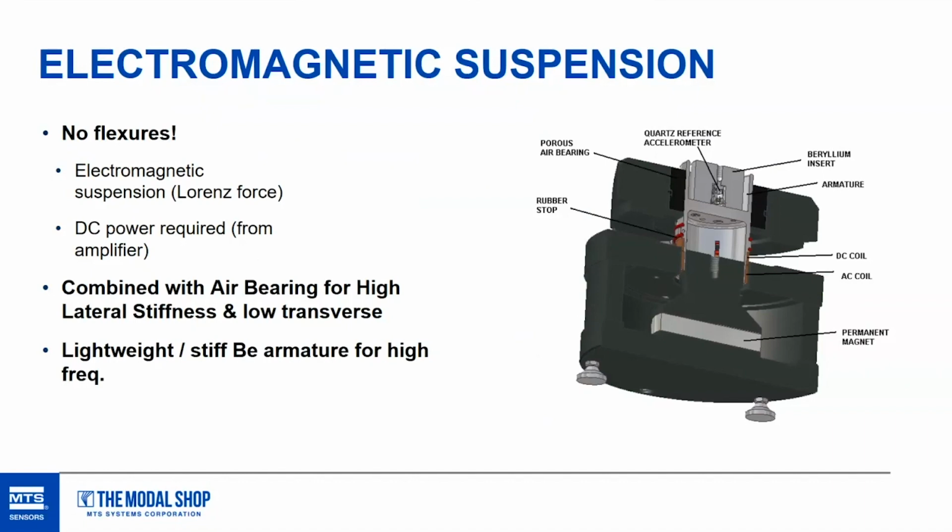The shaker is only going up and down and almost not having any type of jiggling or any transverse motion that can affect calibration. And that's a pretty common issue with flexure-based systems, flexure-based shakers, but with the air-bearing design, you pretty much eliminate that and keep the shaker under the ISO